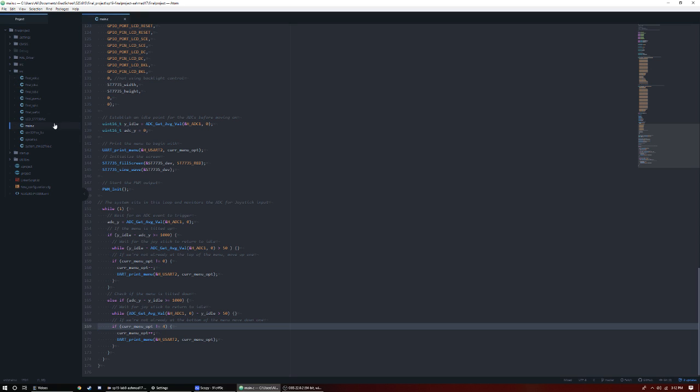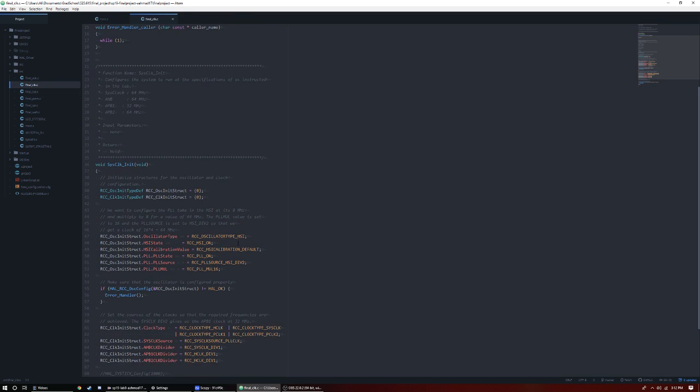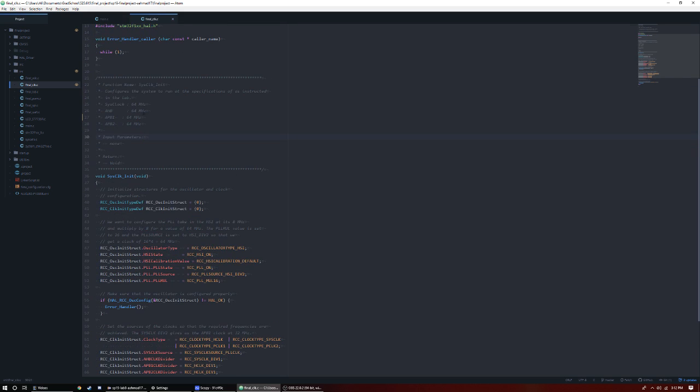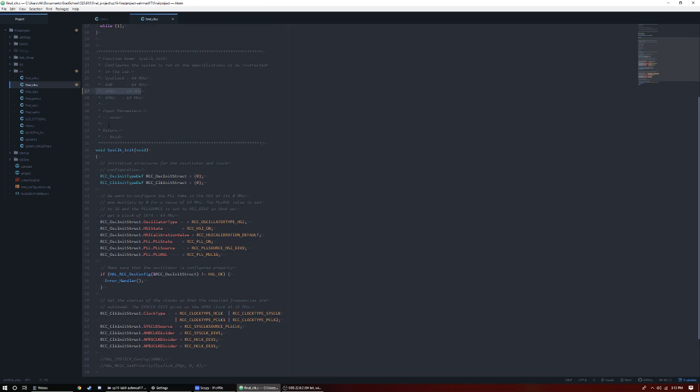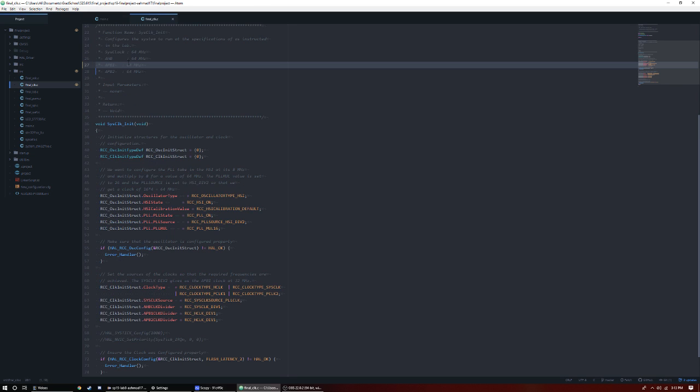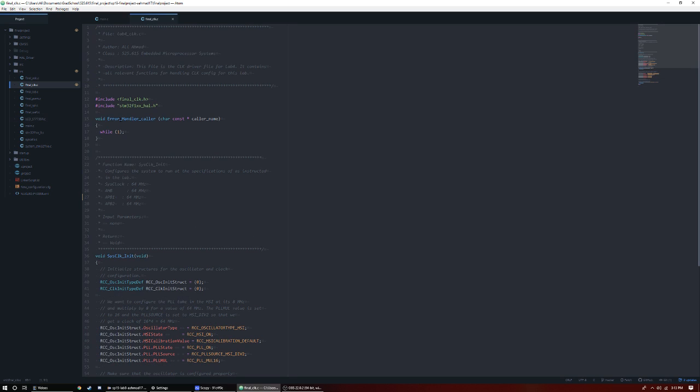So moving on, I'll start with the clock configuration because there's a few changes from what we had before. This needs to say 64. Basically, what I have is the clock initialization that we had from the very beginning of the class. Everything, however, is changed to 64 megahertz. Previously, we were using APB1 set to 32 megahertz. I have it set to 64 to give me greater frequency output on the PWM, since timer 3 is hooked up to APB1 in the clock tree for the STM32. That's the only change here.